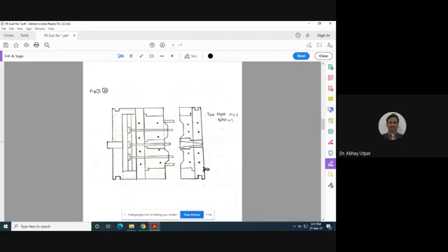The next criterion is whether the parting line is regular or irregular. Then the next is the method of manufacturing: how the mold is made, just by machining or casting. Then the runner system in the mold. If you see the mold, the runner system is itself machined in that right hand side plate. See here, I will show. This is a screw.